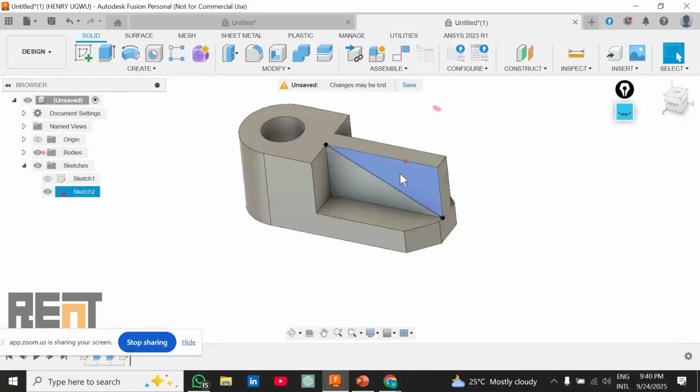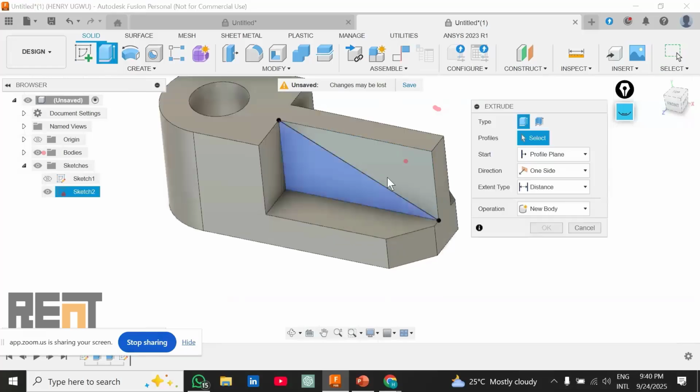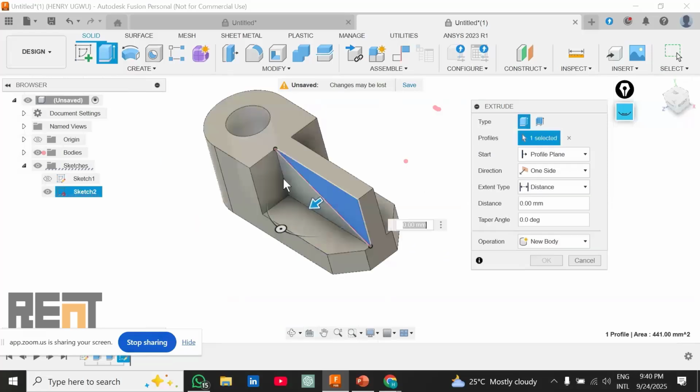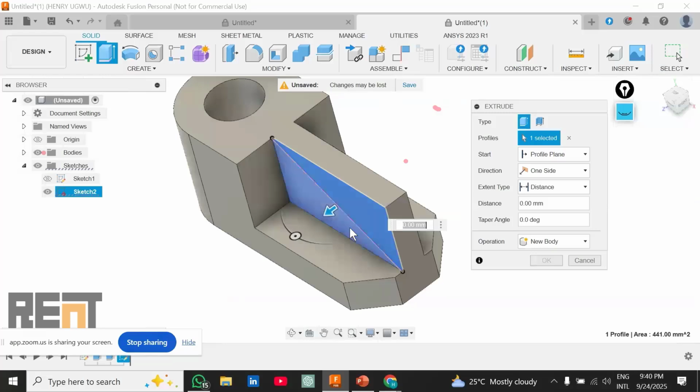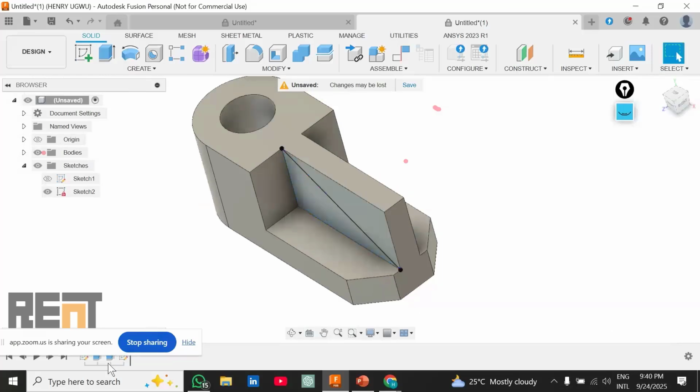All right, let's try and extrude cut this operation to leave us with this other one, thereby giving us a steep surface. So I'm going to select extrude and select the surface. You can see it selected the surface even by using that line to divide it. In some cases, you might try, it might not work. So let's go back to the sketch.